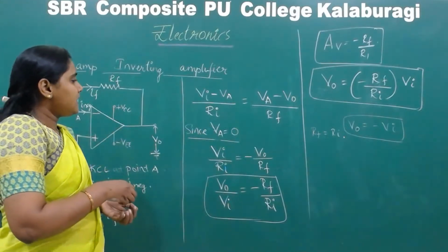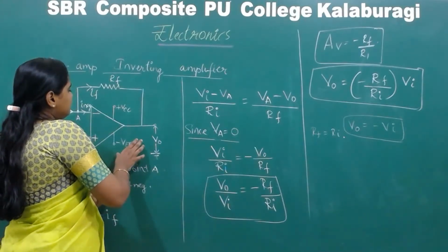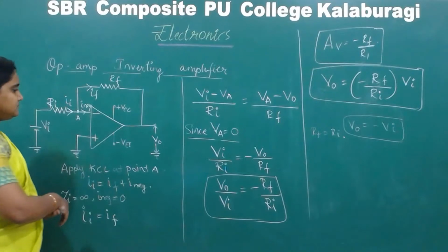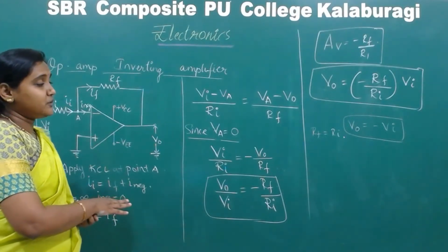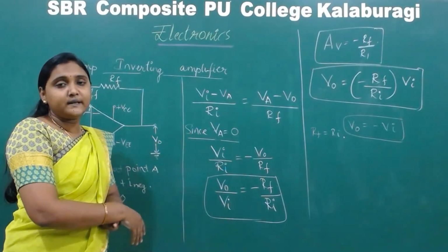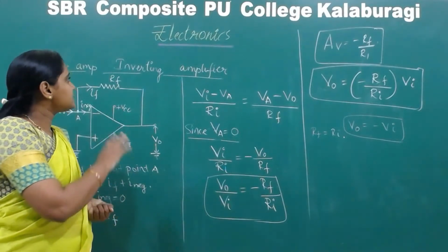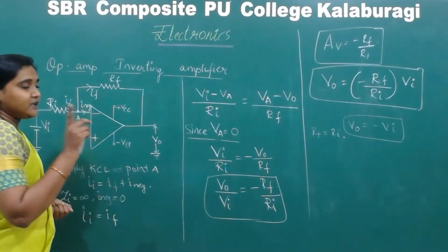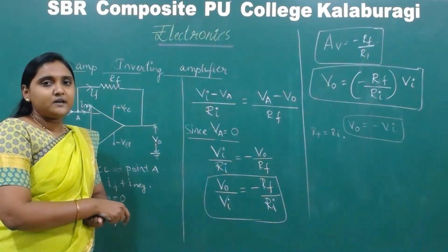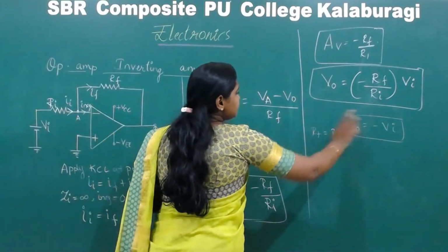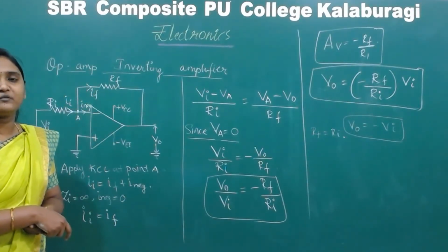So this circuit is very useful for designing an amplified signal, and for designing a signal with inverted output without any amplification or without introducing any gain. So this is all about the op-amp inverting amplifier, starting with the definition, the circuit, the derivation, and the output. What we observe here is that the output is minus of the input, that means the inverted form of the applied input.